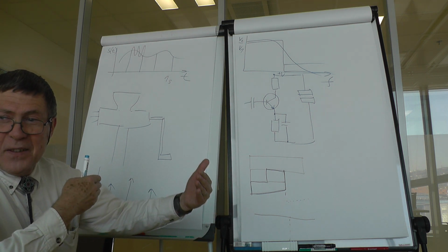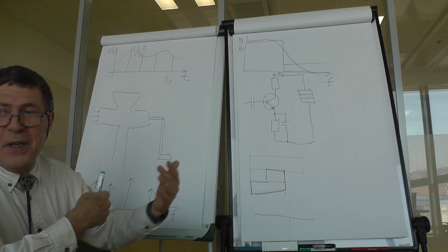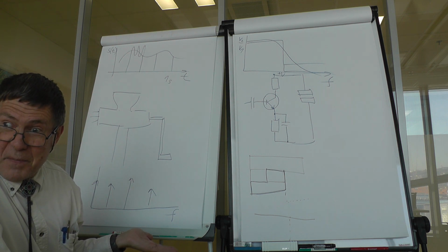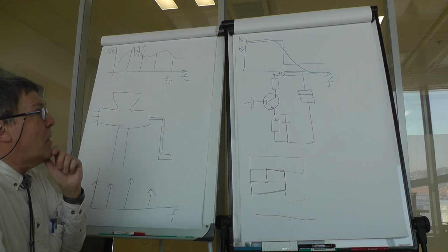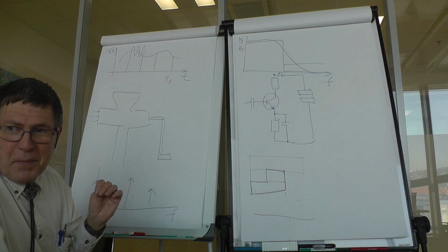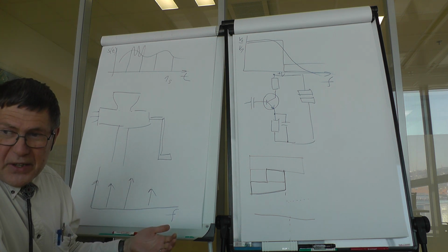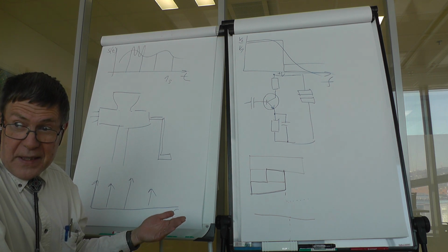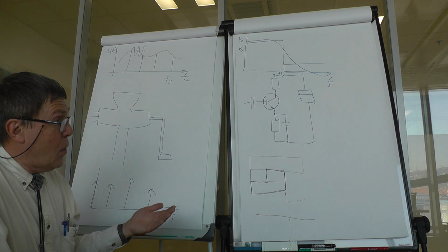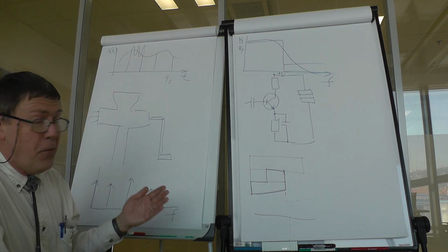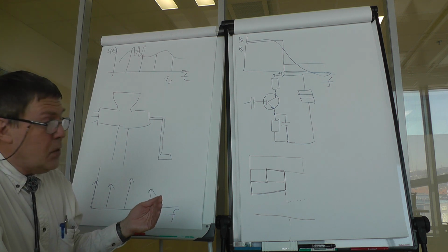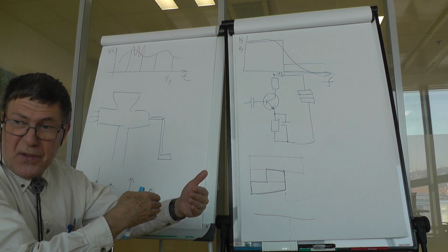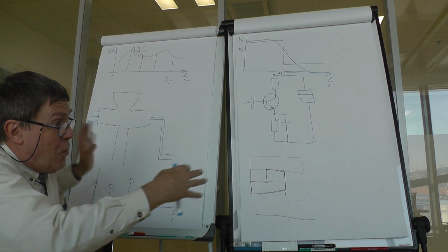So if you undersample a signal and use a Fourier transform, you would get complete nonsense. Now this is tricky because you possibly know that at nonlinearities mostly all harmonic components are present. So unless you provide a fine sampling, you will neglect some important parts of the energy of the signal, and that would reflect somewhere into the spectrum.